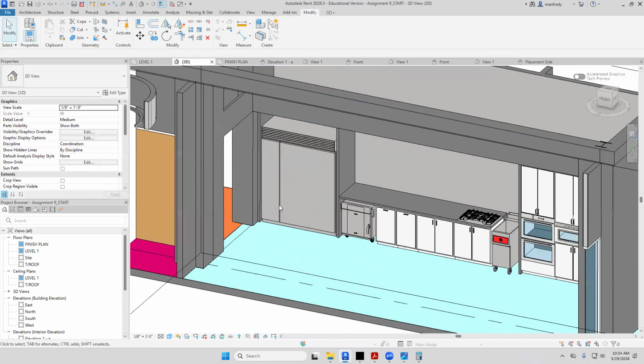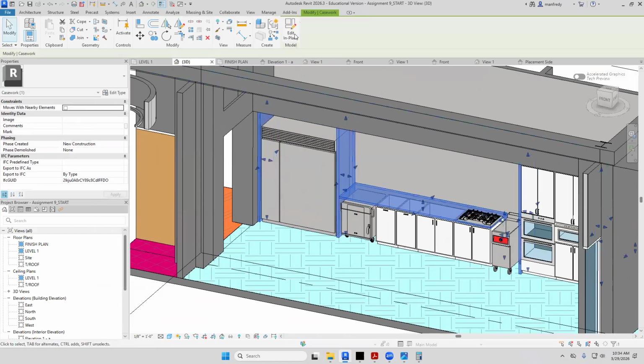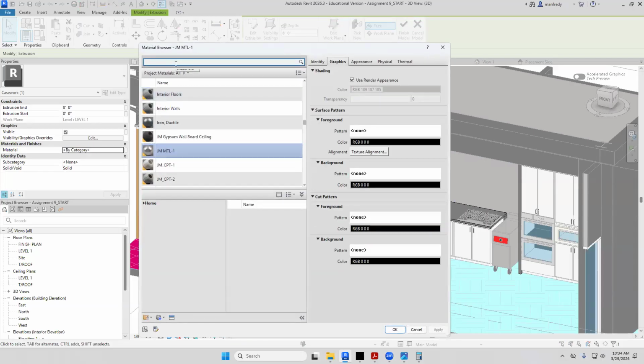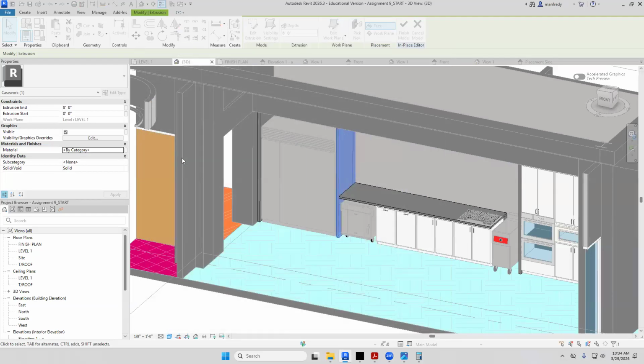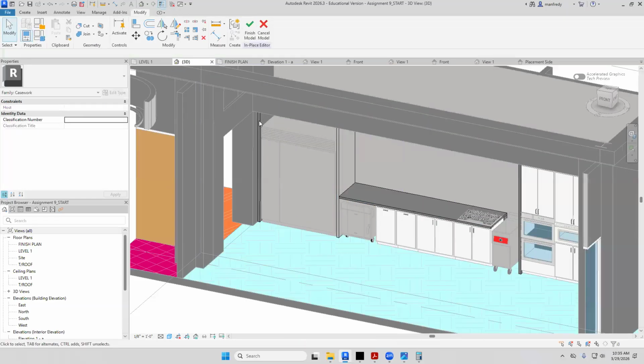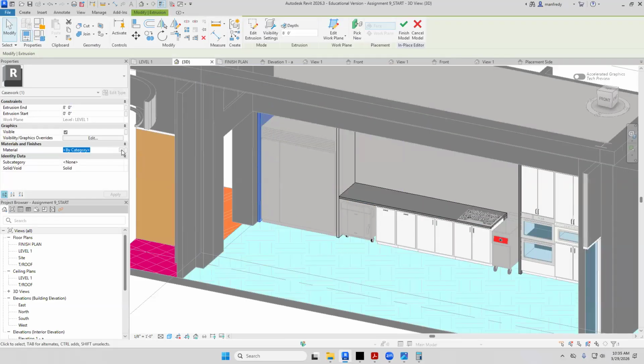When you want to change your models, like this model here, for example, under model edit in place, you click on it by itself and you put the material there. So here, I can put metal number 1, and it'll put on all sides. See? So then I can just simply go into here, grab this one, put it here.